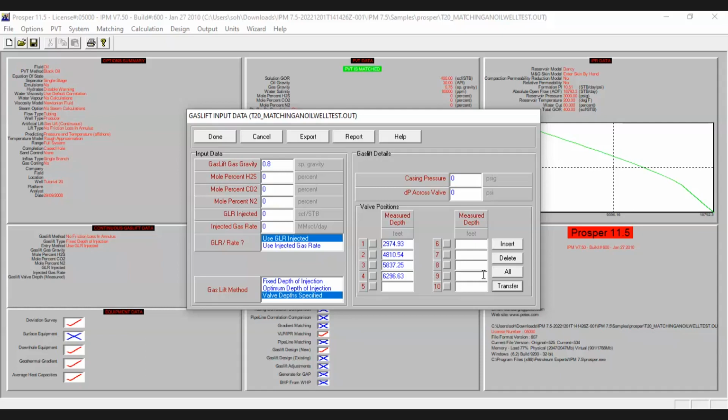Okay. The right answer is that we are not considering the orifice, which is the bottom-most valve, as an unloading valve. So we have 3 unloading valves and 1 orifice, which is our injection or operating point. This is always operating, so it's not going to be closed.